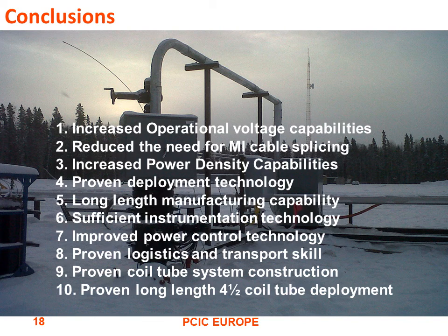This is sufficient instrumentation technology. As I said, the downside was that the DTS didn't operate, but we had it backed up with 24 thermocouples, which gave us the information we needed. And the DTS system will probably be too expensive for commercial applications in the long run, but for a diagnostic and a pilot, it could give you some good information. We improved the power control technology. We proved that the variable voltage transformers were adequate and very good, actually, from an economic standpoint in this application.